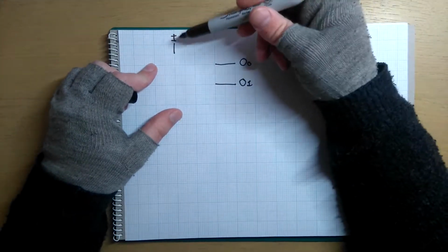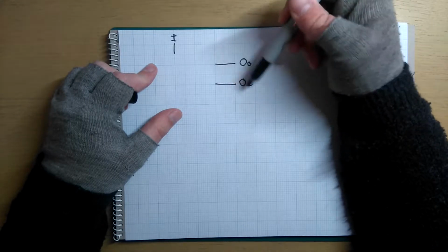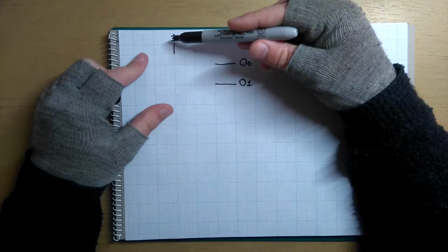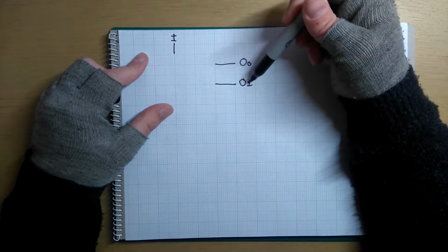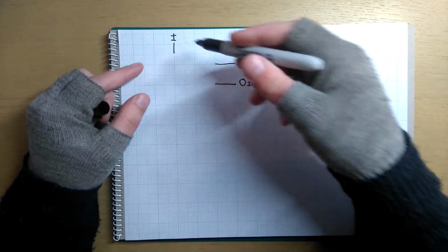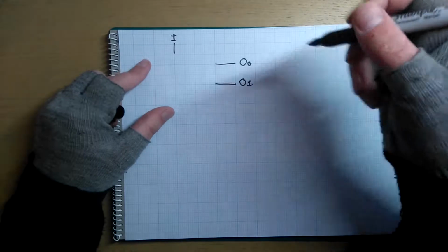Right, so the idea is that when this is 0, output 0 is 1, and the rest, whatever else is left, is false or low. And when it's 1, this is low and this is high. So it's like a counter. It will just count whatever's in binary here, and output just one line on this side.